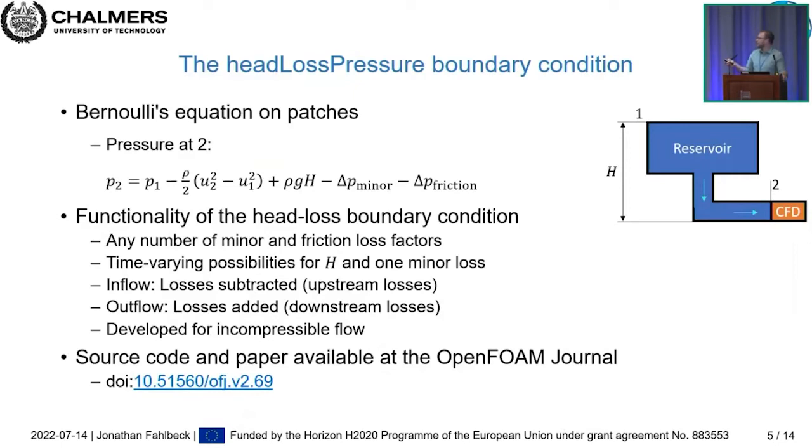So the question is basically how I calculate this term, right? So I use the Colebrook equation, and solve the friction factor iteratively with this boundary condition. So it will be a function of the flow rate, diameter, and surface roughness in the parts that are not included in the numerical domain. So in this boundary condition, you need to specify the length of the pipes, but also the surface roughness. But then the flow rate will come as a result of the balance between pressure in the system. So the friction factor is solved iteratively in the boundary condition.